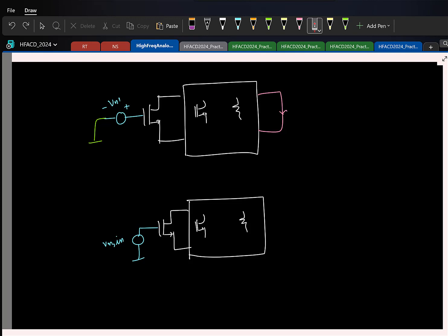Or let me put it this way, let us say there are no noisy elements in the network, right? This is the only transistor contributing to noise, right? So technically what I'll do, I'll find the short circuit noise divided by the transfer function and then model it as an equivalent voltage noise like this. So can you see what that will be?